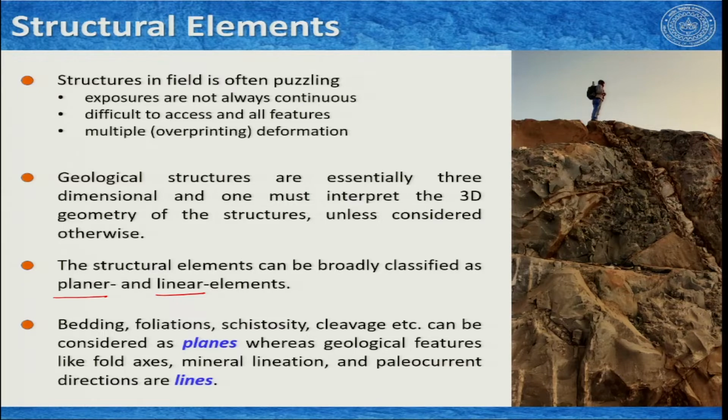In the planar elements, we consider different planes, where we have bedding planes, different foliation, schistosity, cleavage planes, etc. And in the linear features, we have some geological imaginary directions like fold axis, but we have some physical directions like striations due to fault movements, we have mineral lineations and many other things that are considered as linear elements of structural geology.